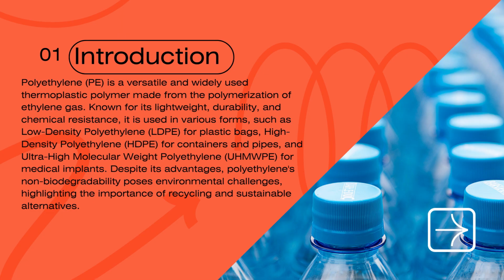Polyethylene is a versatile and widely used thermoplastic polymer made from the polymerization of ethylene gas. It is known for its lightweight, durability and chemical resistance. It is used in various forms such as low density polyethylene for plastic bags, high density polyethylene for containers and pipes, and ultra high molecular weight polyethylene for medical implants.